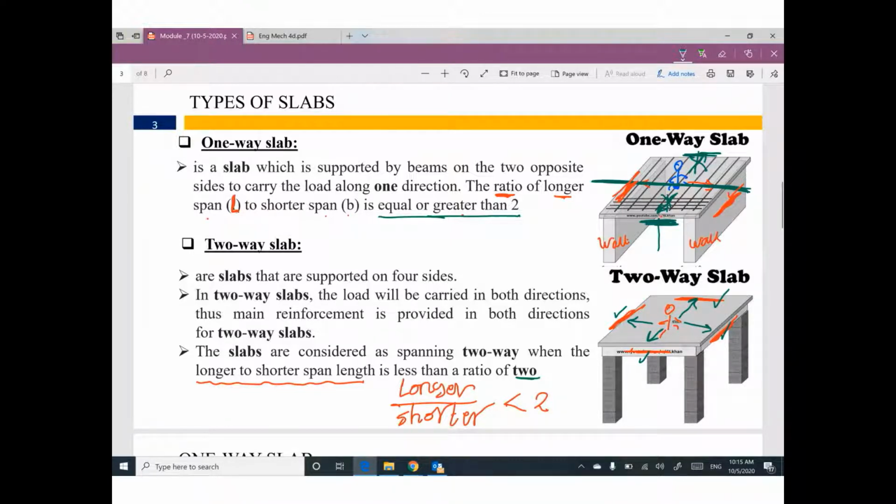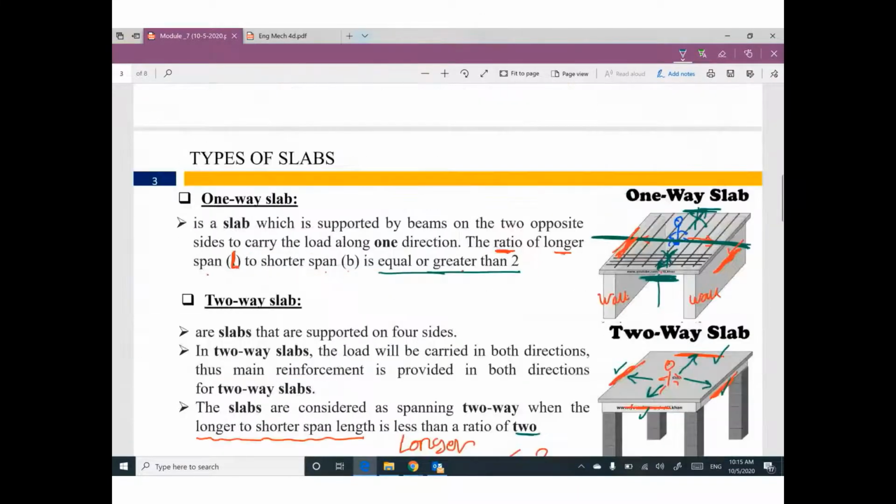I'm gonna start with one-way slab. Most of the time, this type of slab exists in bridges, garages, this kind of building, where we can expect heavy live load. But in office buildings, hospitals, probably hospitals also one-way slab. But office buildings, residential buildings, the typical building, two-way.